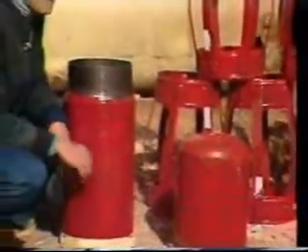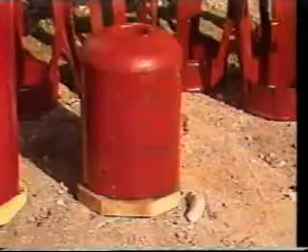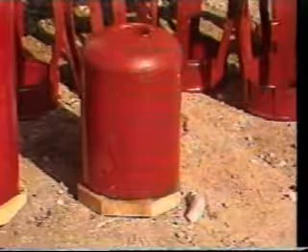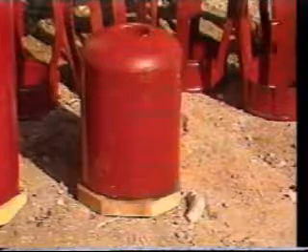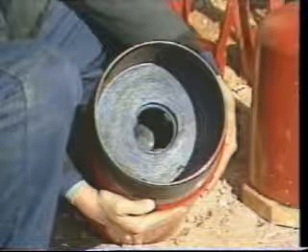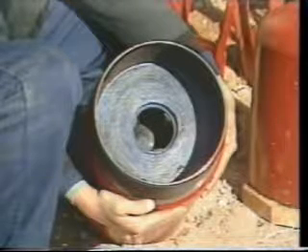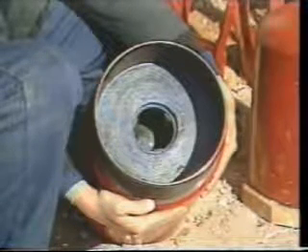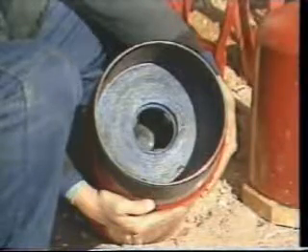After we run our large diameter surface casing, we'll be running a smaller diameter, in this case 9 5/8 inch casing, inside of it. We'll also have a guide shoe on the bottom of our 9 5/8 inch casing that'll act just like the guide shoe on the surface casing. A float collar placed several casing lengths above the shoe contains a one-way valve which allows the cement to be pumped down the casing but does not allow drilling fluid or cement to flow back up inside the casing.